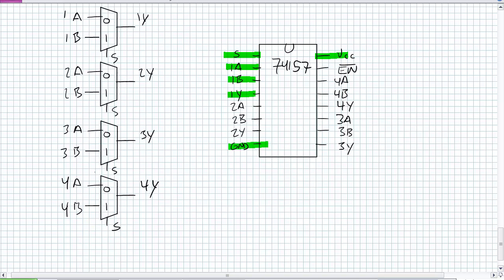You'd have to look into the data sheet for it. However, you can also use the ANSI IEEE logic symbol, and it's neat because it's got this common control. And one last thing I forgot before I go into that, it's this enable, and notice it's got a low bar over it, basically a negation bar over it. For this thing to work at all, that enable has to be tied to ground or given a logical 0. So I can turn the thing on or I can turn the thing off, potentially even using 2 of these guys in combination to route 4 separate BCD numbers to a single display.